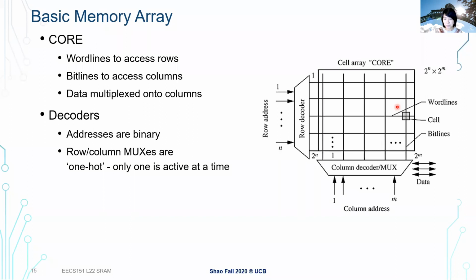So in today's lecture, we'll be mostly focusing on the cell design, what's really inside this cell so that we can store data, and not only store data, but also make it accessible so that we can read the data out, like doing a memory read operation, and also update this data, like write to this memory so that we can update the value in this cell. So we'll start with the cell structure, how we build this internal storage element in our SRAM.